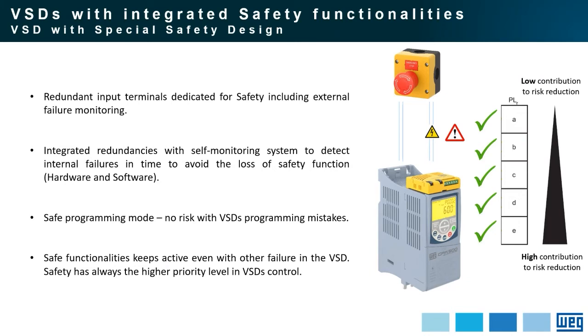It means the same thing that external safety relays will do, the variable speed drive is also capable of doing: checking if the cables between the variable speed drive and external safety components are healthy.